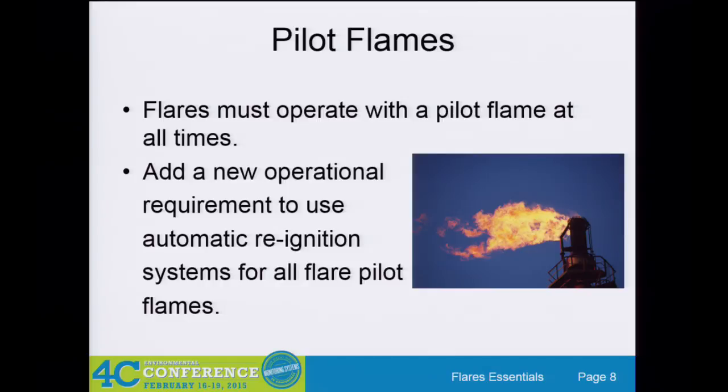Pilot flames. Again, you've got to have that pilot flame at all times. But now they're adding an additional requirement. Not only do you have to have a pilot flame at all times, you have to have an automatic reignition system to relight your pilots. It's no longer, I have a flame front generator, if the pilot goes out, I get an alarm, call the operator, he walks over to the panel, mixes the gas and sends it up there. They say that is too long. They're very concerned about any periods where you could not have a pilot flame on your tip. So they want those systems to be automatic.